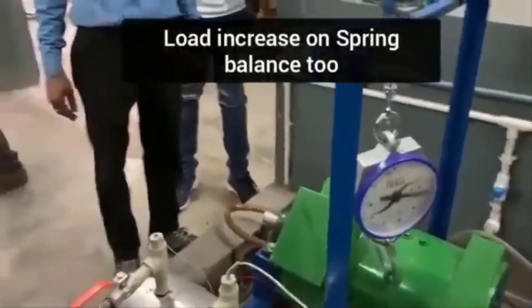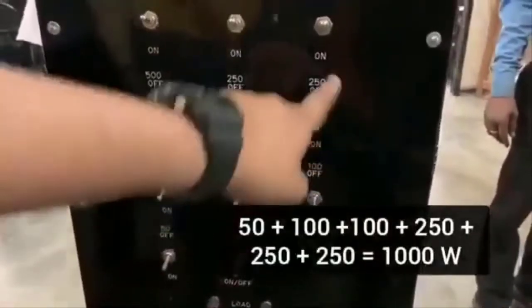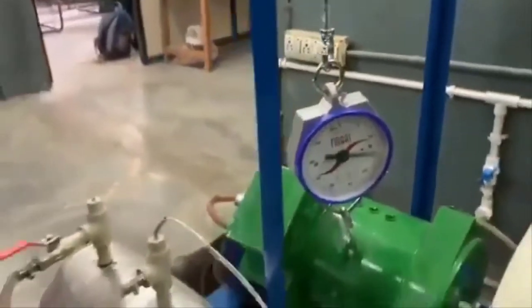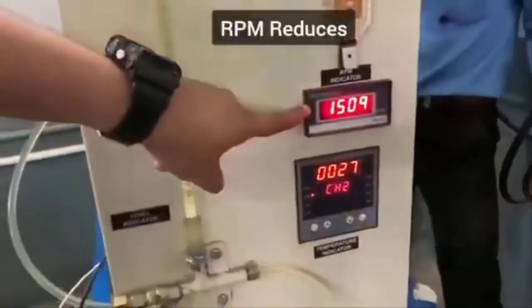So we will see this on a spring balance that now the engine is in stable condition. We have applied 50 plus 100 plus 100 plus 250 plus 250, that is 1000 watt, that is 1 kilowatt. And the same is reflected on the spring balance. Now we will note down the RPM.